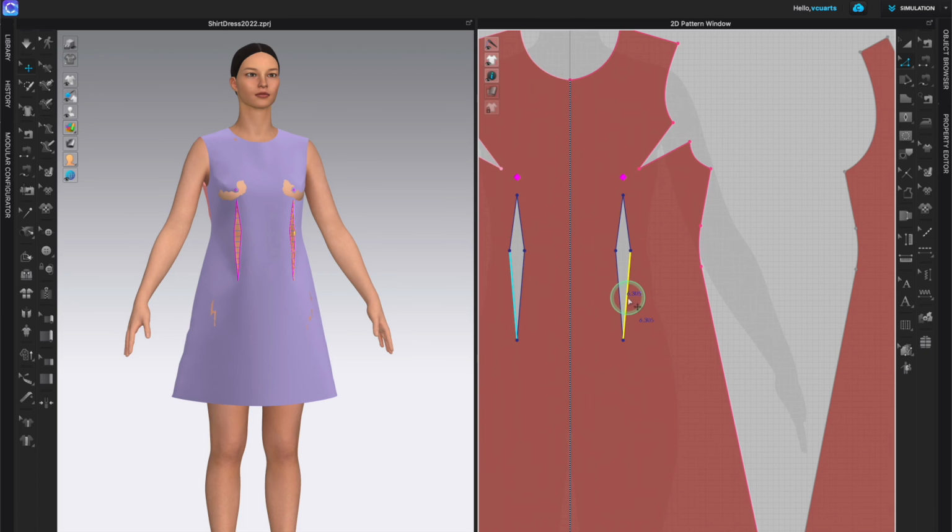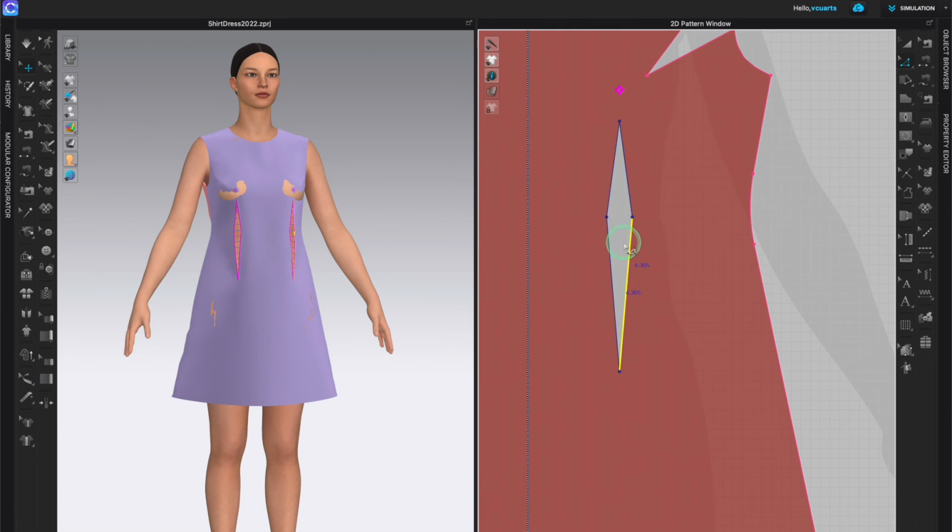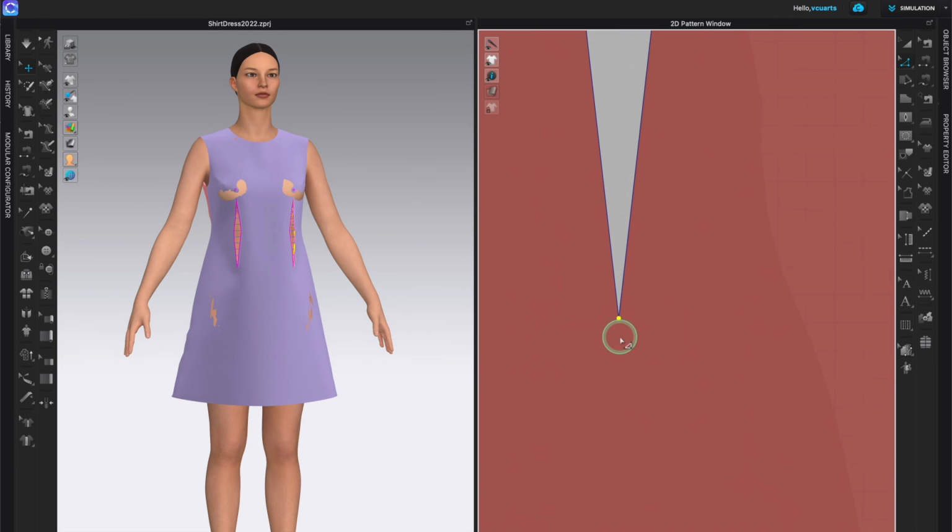And then let's see how long this is. So 6 inches. Let's move this up a little bit. And while I do this, I'm going to hold shift so I can lock into that angle. And I'm gonna do a full 5 inches. It tries to fight you a little bit sometimes when you have the restrained axes in.